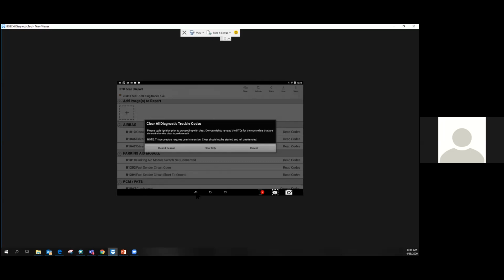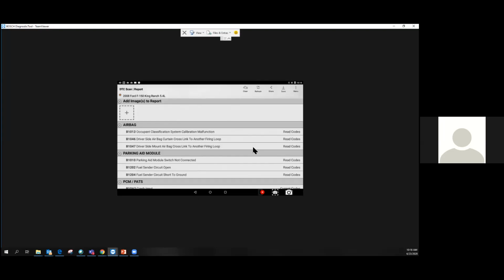which actually brings up another point of when to perform the post-scan. So obviously when the repairs are done, you want to do your first post-scan, right? You want to make sure that all your work is done, all your faults have been cleared, all the necessary components have been replaced. Now, if you do clear all those fault codes out and you have a clean report, now it's time for a test drive, right?